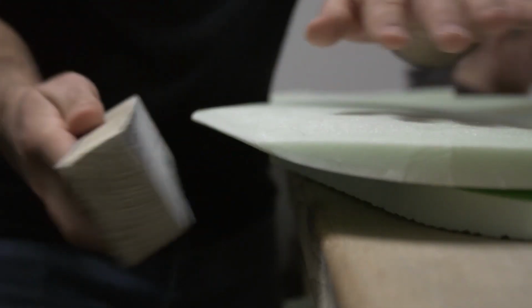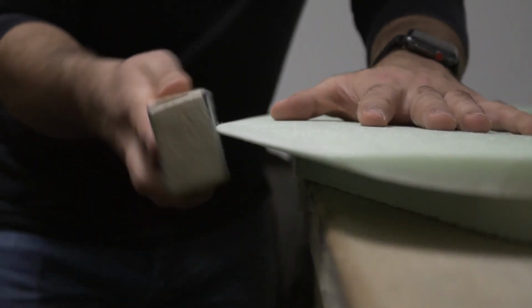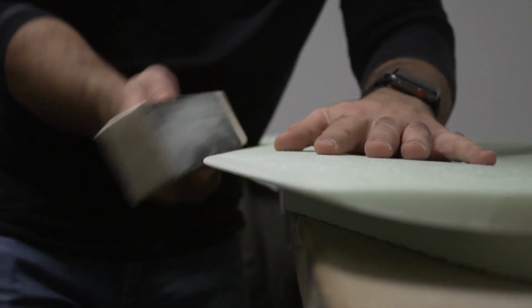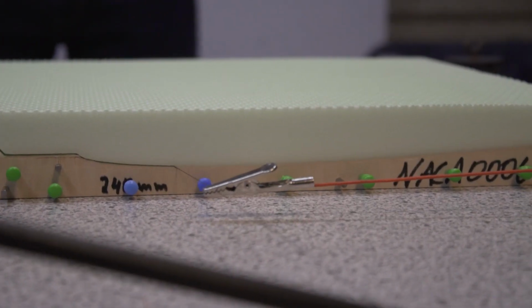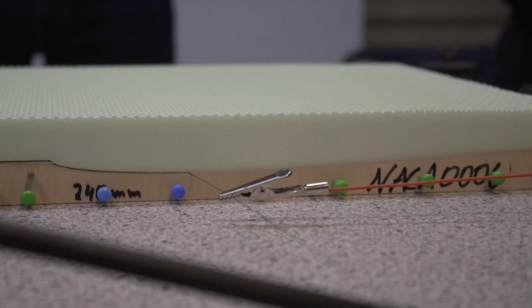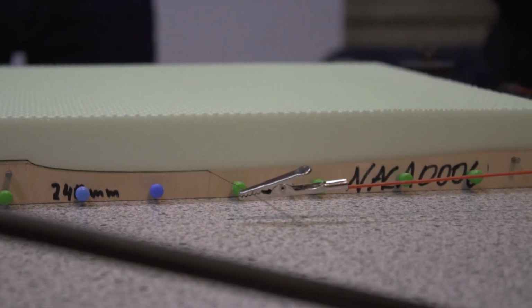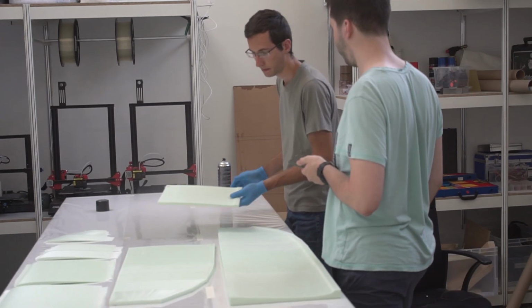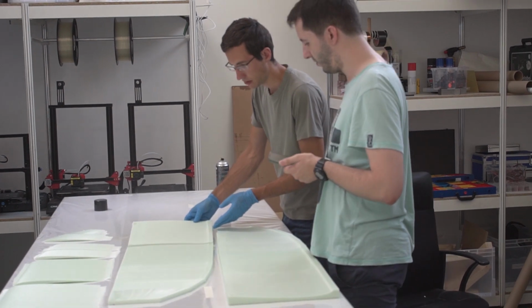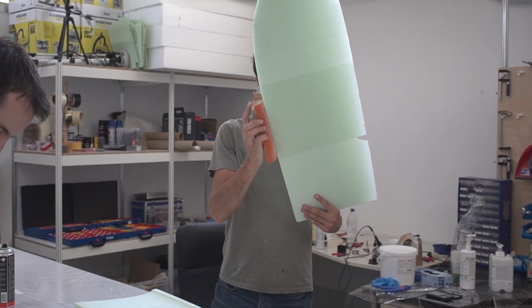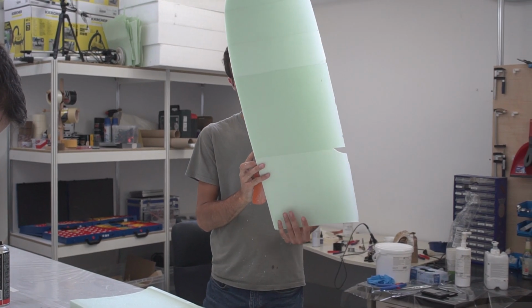As an alternative, we decided to build the main wing in the foam core process, which we used many times in the past. We used a hot wire and templates to cut the foam core of the wing in multiple segments. The segments were then glued together and sanded. We then added the pockets that would hold the wing spar, as well as wires and mounts for the servos.